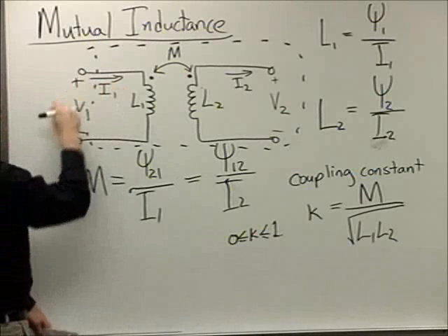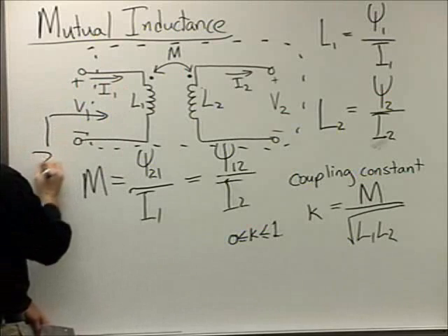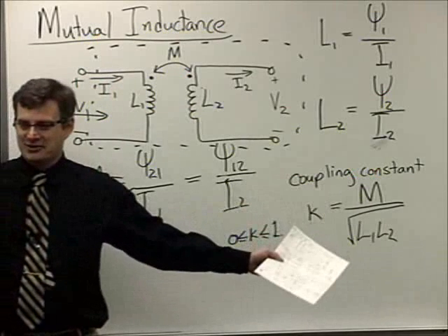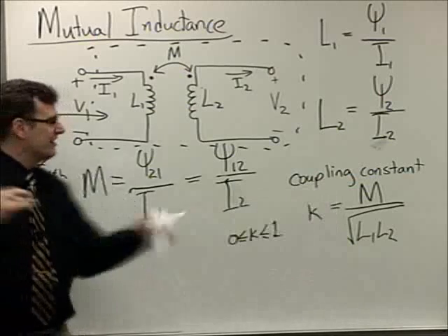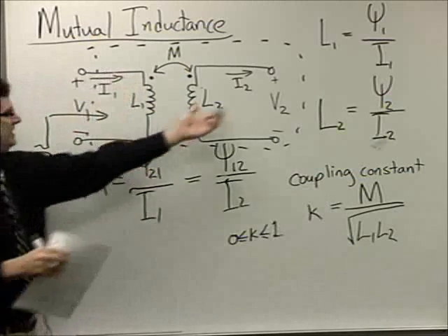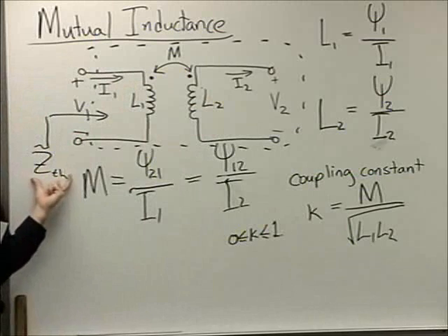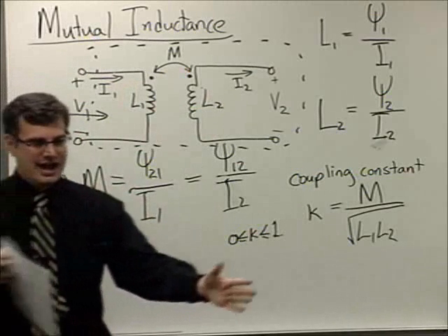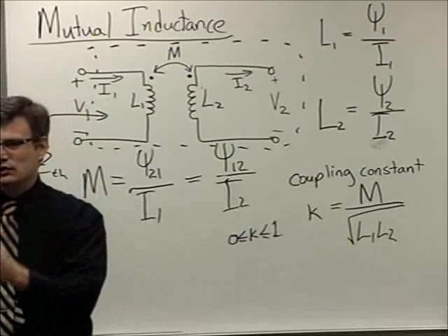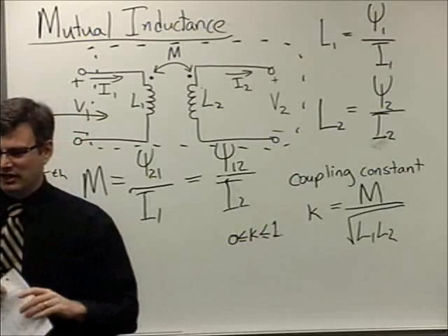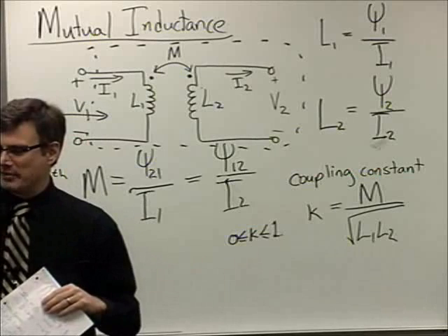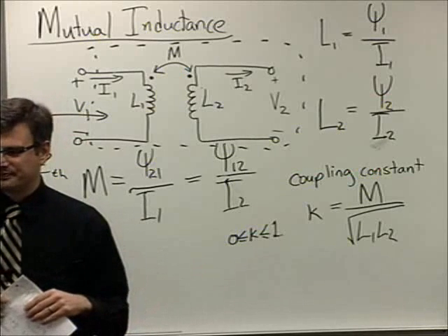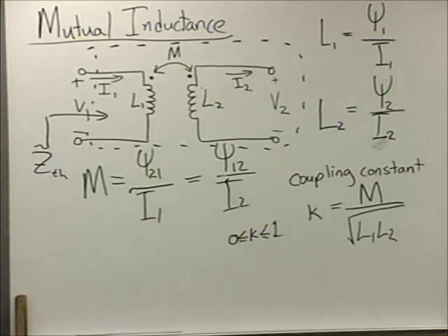Because once you get the Thevenin equivalent of that system, you've characterized the entire system, right? You can analyze this. If I say, oh, this system is behaving like this. So this is the beauty of electromagnetics. We're going to start with physics, and we're going to march it down so that you have a useful circuit model. And you can relate the physical parameters to the electrical parameters that you would put into SPICE or do your analysis with.